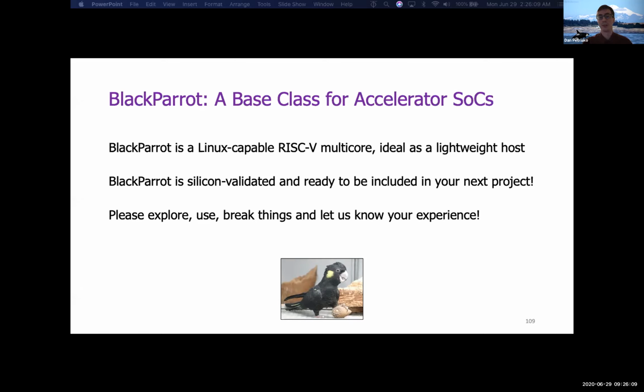We do run using OpenRoad internally just to validate that the flow works. And then for simulation, we support both VCS and Verilator. So when we run our test regressions, we make sure that works in both. And we've actually uncovered half a dozen bug fixes to Verilator that we've contributed back to make sure that it keeps working, which is a pretty cool contribution.